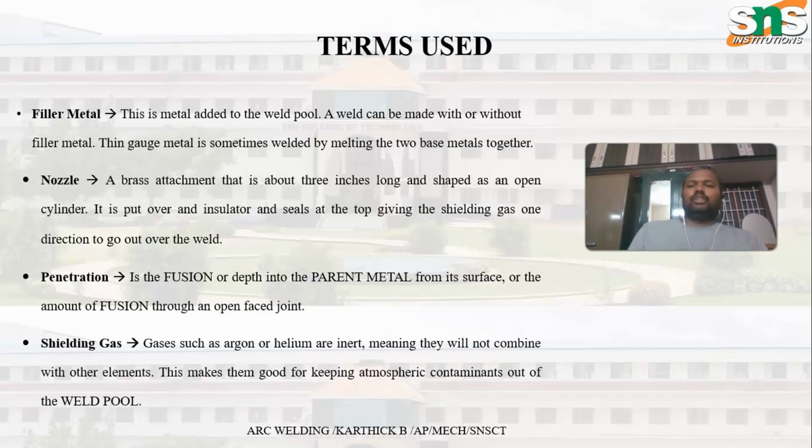The next one is penetration. When welding is done, not only the welded area, the heat or the weld metal gets deposited, and sometimes it penetrates through the parent metal from the surface. This amount of fusion that happens is the penetration.